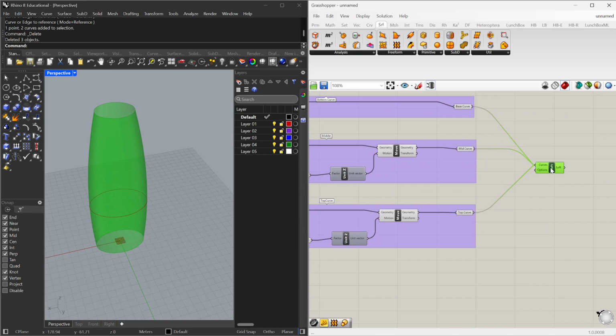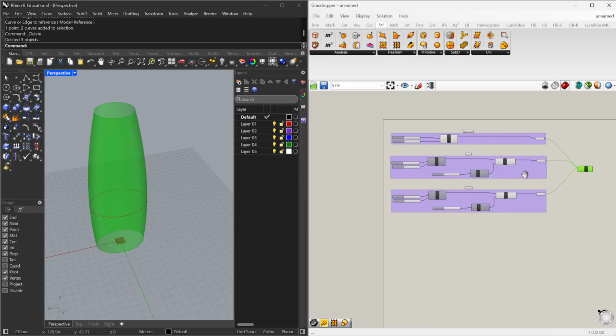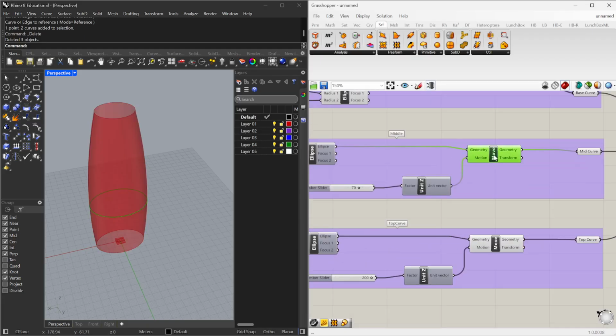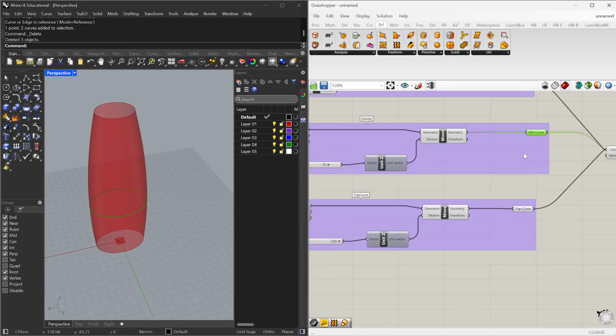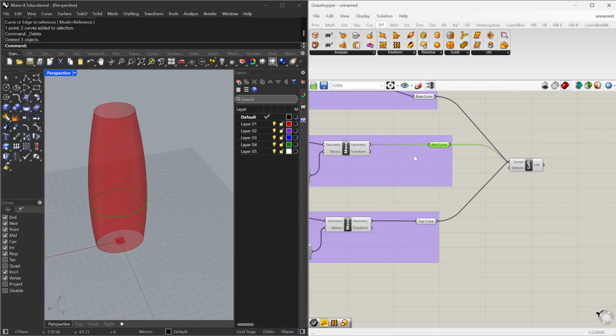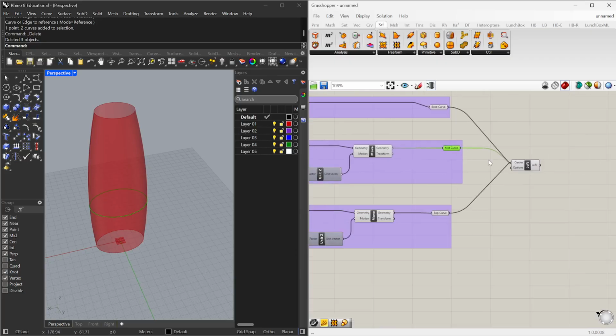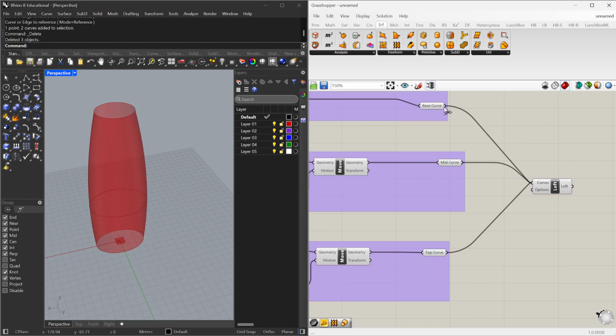Okay? Now let's say that I want it to be a twisted tower. What I can do is I can take these curves before they move and I can output between here and here a rotation. So I can start to then rotate it, and then I can bring that rotated curve into my loft, and then I can add rotation as well to my curves. So in order to do that, let's just undo our loft by just holding control,